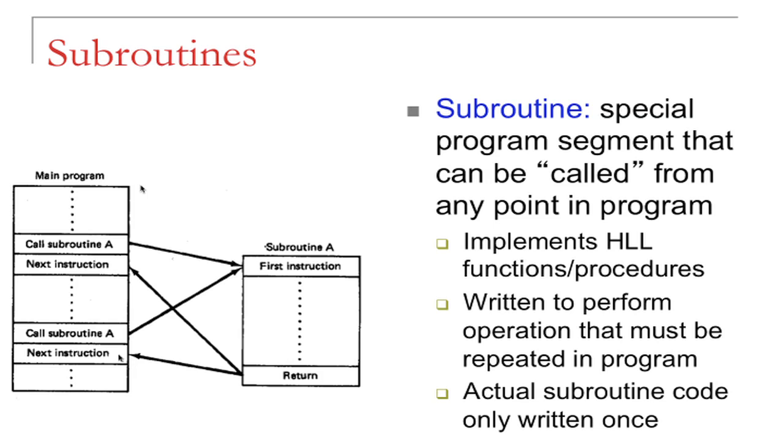So after the subroutine instruction, always have the return code, right? Yeah, so the comment is, if we use call and this return, every time after the subroutine is finished, it will have this return as its last instruction, and this last instruction will take the microprocessor back to where it made the call.